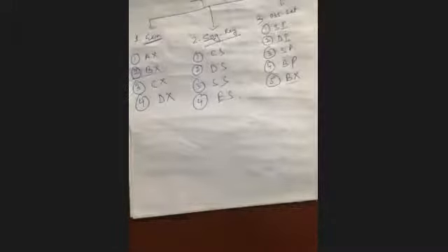Am I right? Yes, sir. Some 16-bit registers are also there, like BC, DE, and HL. These three are register pairs. Other than that, PC is the program counter, and SP is the stack pointer. So a 16-bit address can be located by a 16-bit register, right?